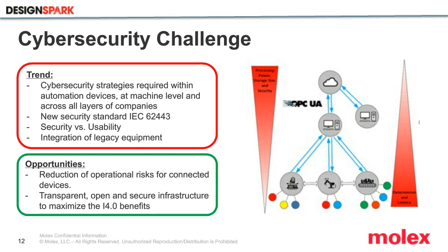So increasing the communication capability and the openness of the industrial networks increases as well the risk of attacks on these applications. We see that the security strategies already in place in the IT world will move more and more into the OT world. New standards like the IEC 62443 were released, which defines how security should be managed in manufacturing installations, from the security processes down to the security requirements of devices.